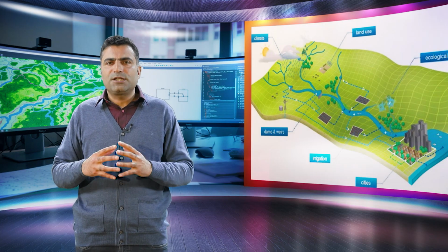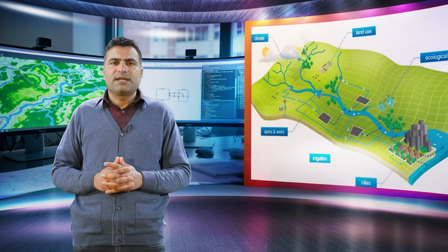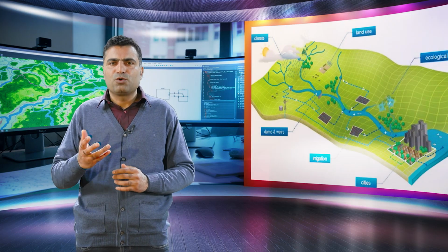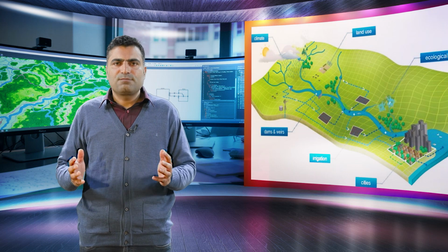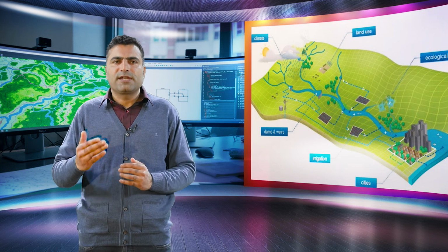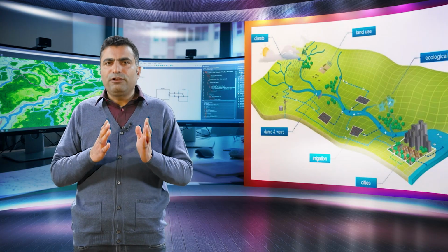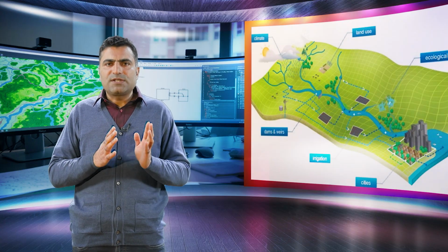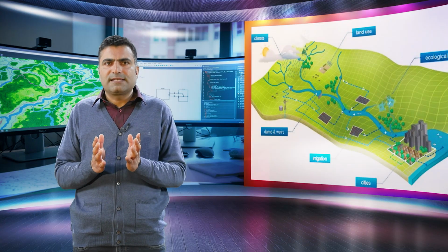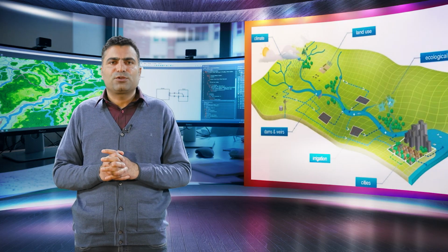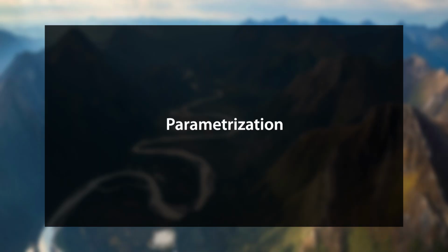Now, so far as the importance of scale is concerned, the size and spacing of these discrete blocks are critical because they determine the resolution of the model's output. If flow paths, that is the movement of the water, or hydraulic gradients, that is the hydraulic head slopes driving flow, vary widely in a specific area, fine discretization with a small cell size is required to accurately capture those details. If we just talk about parameterization, which is the method used to describe the complex real world